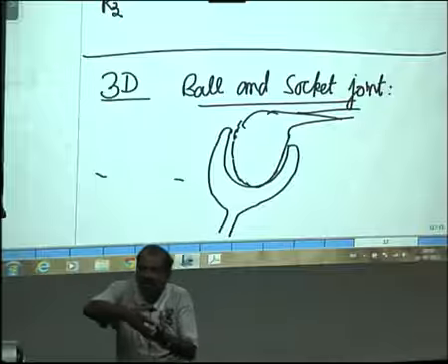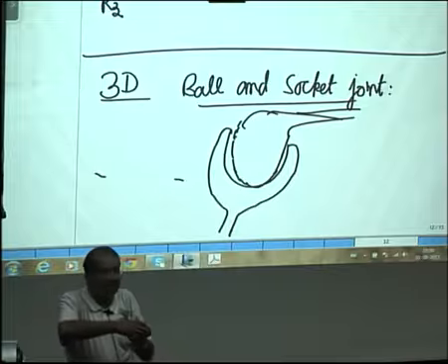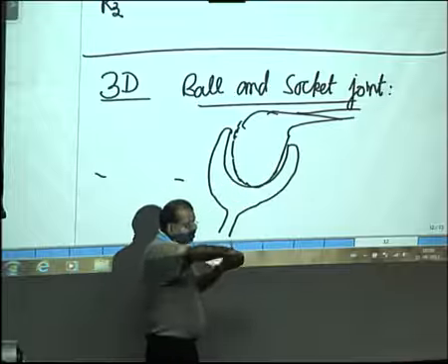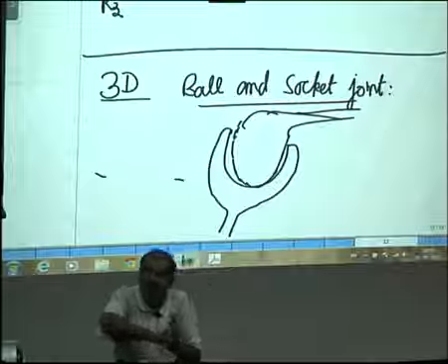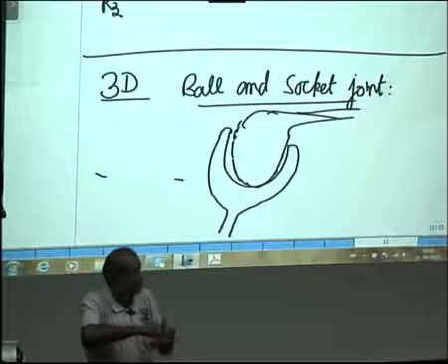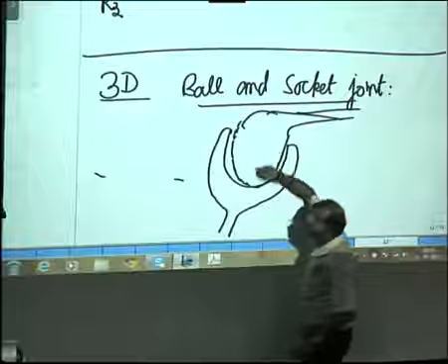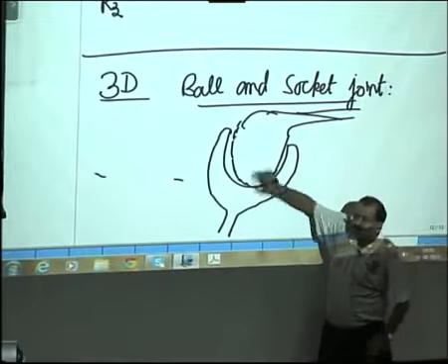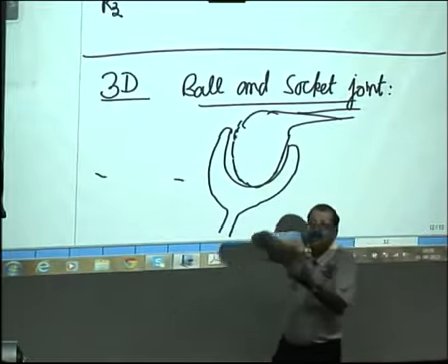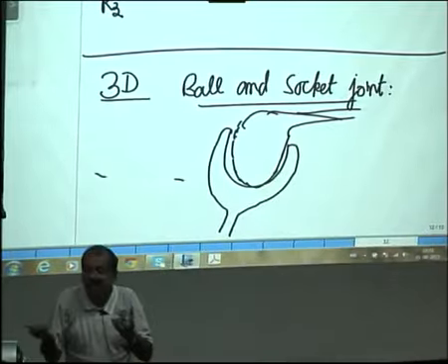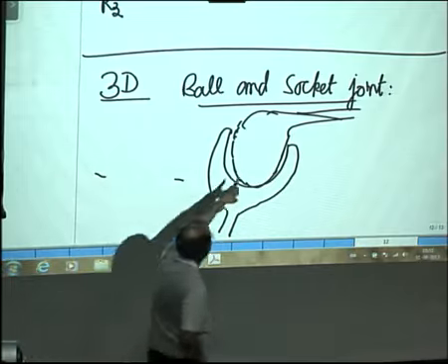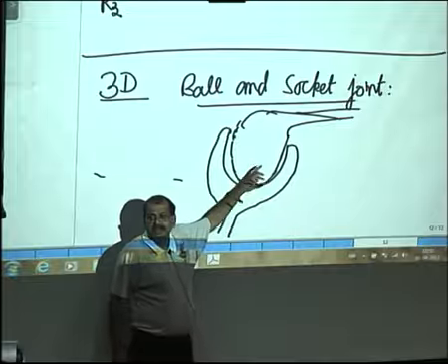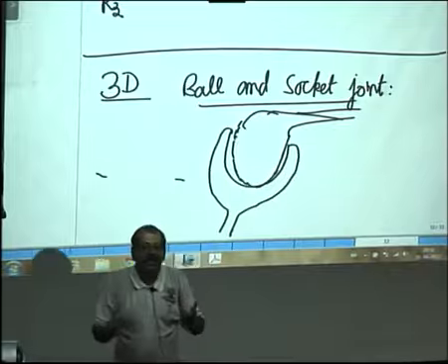Now here what happens is, such a joint will hold the body fixed to this space, but it allows full rotational freedom. This body can rotate about the x-axis, y-axis as well as the z-axis. But because it is fixed with the joint, it cannot linearly move along x, y and z. So when I draw the free body diagram here, what will I get at this point? I will get Rx i plus Ry j plus Rz k.